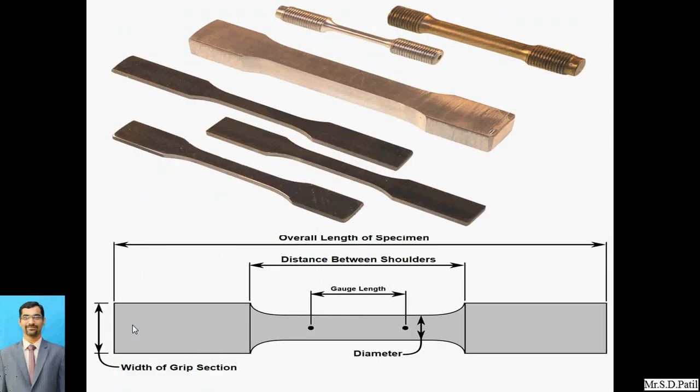So here, first of all, going with the actual concept of testing, we need to know what the various specimens are. So these are the specimens which are shown. We have to manufacture this specimen to carry out the tensile test when we want to know the strength. Likewise, the component may be a round shape, it might have a rectangular shape, or might be a flat shape. So these are some realistic components which are manufactured just to carry out the tensile test.